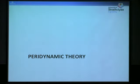And this is a beautiful equation, used in things like finite element analysis and so on. We are trying to solve this equation, but this equation has a little problem. The problem is coming from the second term, and as you will see, this term has a spatial derivative in there, and whenever we have discontinuities like cracks, then we cannot calculate this term. Then we need to use some other techniques, like linear elastic fracture mechanics, and as we saw earlier, the cohesive zone model and so on.